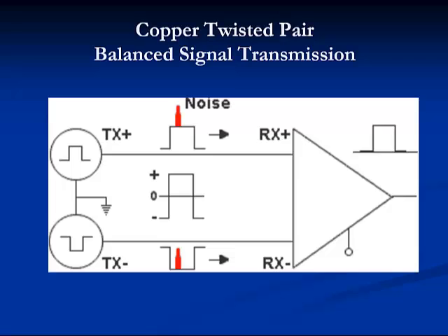You're likely to experience crosstalk on a telephone. When you hear another's conversation through the telephone, that is crosstalk. Crosstalk occurs when some of the signal being transmitted on one wire pair is transferred over to another wire pair. When a wire pair is in use, an electrical field is created. This electrical field induces voltage in an adjacent pair with an accompanying transfer of signal. The more the conductors are parallel, the worse this phenomenon is, and the higher the frequency, the more likely crosstalk will happen.